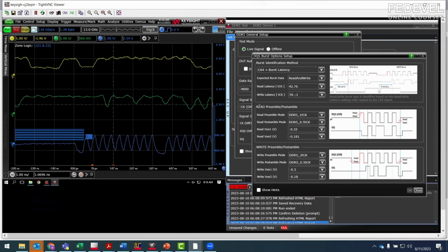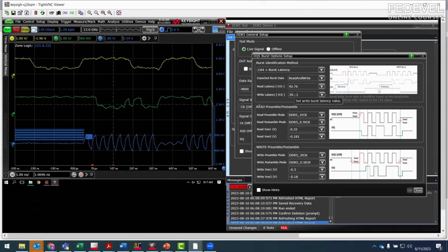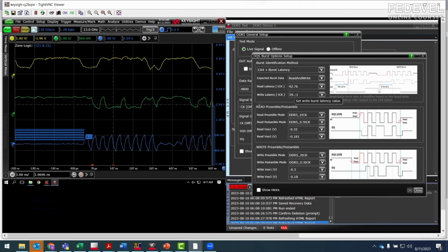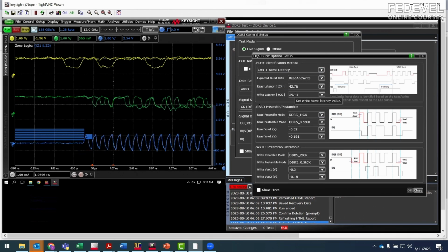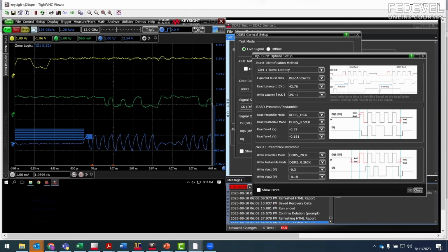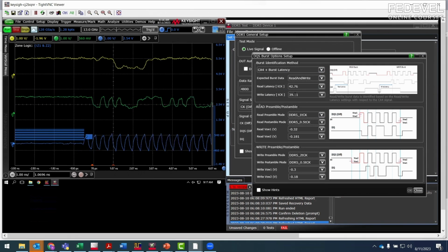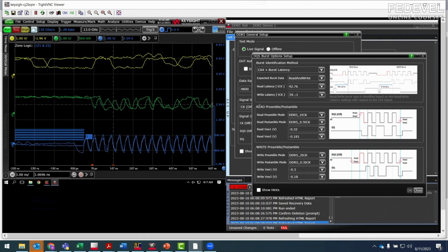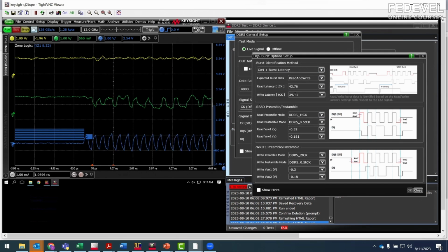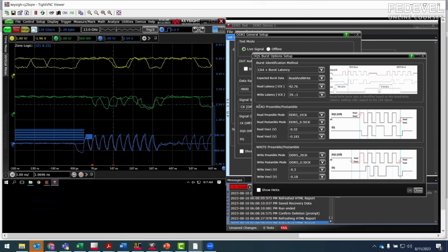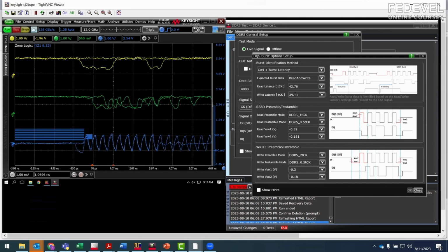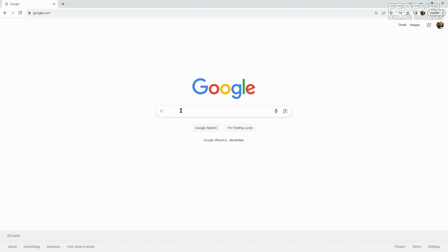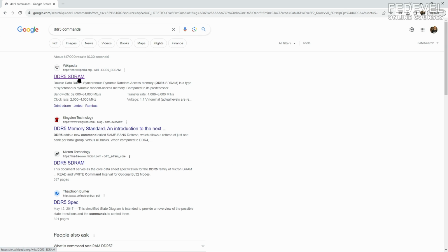I remember the table. The protocol specifies when the read and write is happening, and this CA4 signal is important for this. Yeah, this literally is the read latency. So when this CA4 is happening, it means it's going to be a read or write. And then we have to wait, because the read and write is not happening immediately after this command is sent. There is some delay between what is happening on the address and command bus compared to what is happening on the data bus. Exactly. Yeah, good memory.